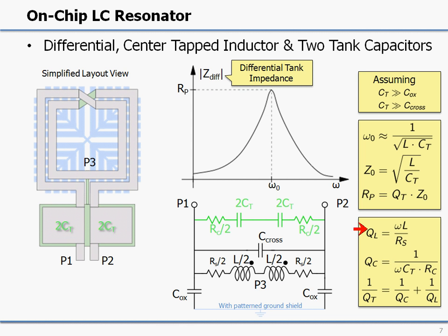The quality factor of inductors tends to increase with frequency to the first order, whereas the quality factor of the capacitor tends to decrease with frequency. What we see is that at lower frequency applications, very often we are limited by quality factors of inductors, whereas for higher frequency applications, the capacitor quality factor can be an issue, or also when we have widely tunable oscillators.